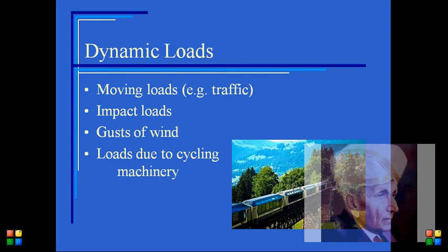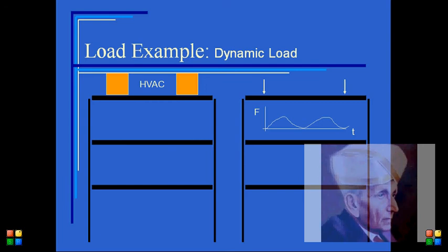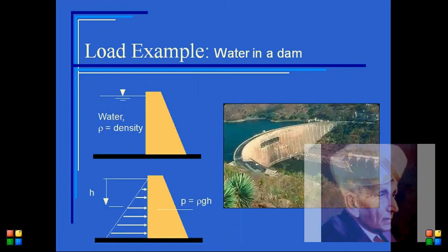Earthquake loads. Structure is loaded when the base is shaken. The response of the structure is dependent on the frequency of motion. When frequencies match the natural frequency of the structure, resonance occurs. Load example, earthquake load, base motion.